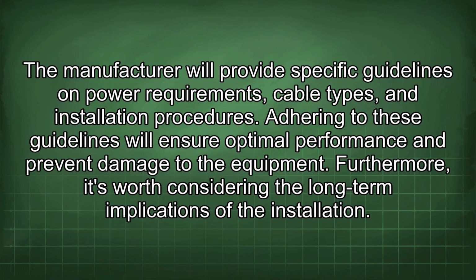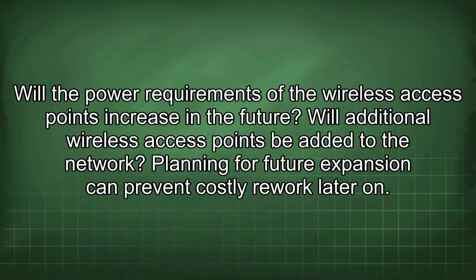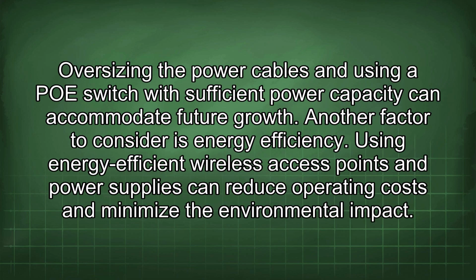Furthermore, it's worth considering the long-term implications of the installation. Will the power requirements of the wireless access points increase in the future? Will additional wireless access points be added to the network? Planning for future expansion can prevent costly rework later on. Oversizing the power cables and using a PoE switch with sufficient power capacity can accommodate future growth.